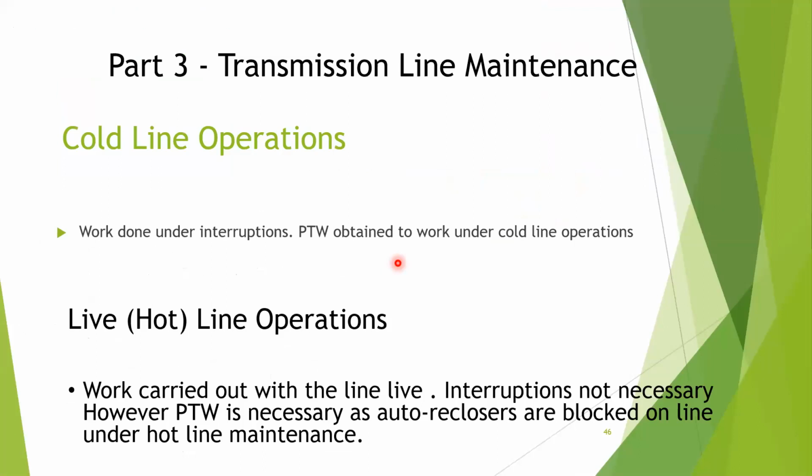Enough of part 2, and now transmission line maintenance. We are starting transmission line maintenance. So line maintenance, we are not going to much details on line maintenance. Cold line operations, work done under interruptions. Permit to work to be obtained to work under cold line operations. You switch off the line and do whatever you want on the line.